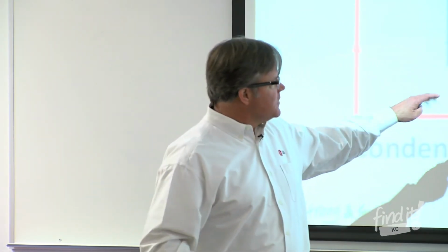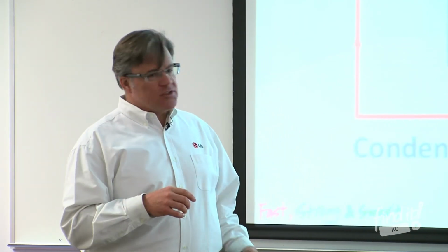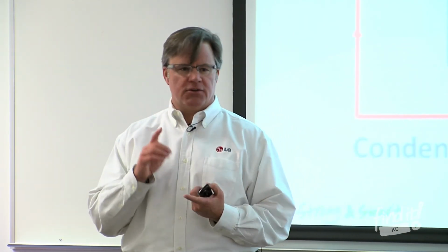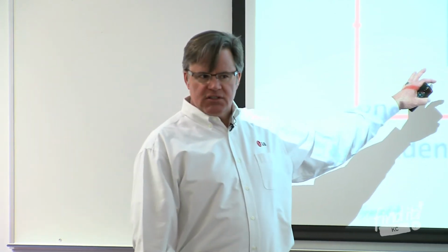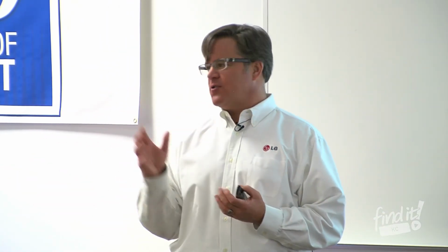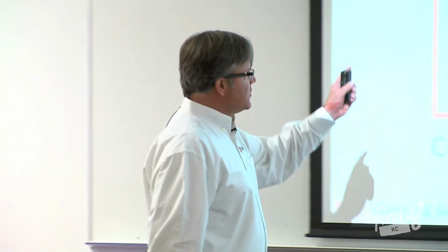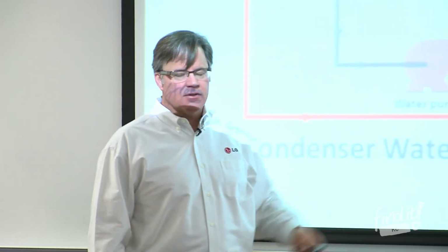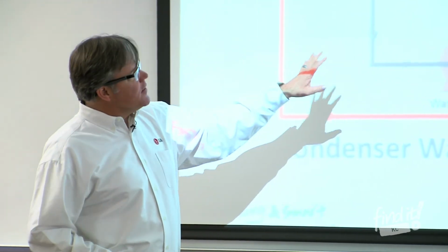This is a very energy efficient way to do that. We also see a lot of folks that deal with buildings in colder climates will go to this type of system, because even though VRF technology will function down to -13, it can get cold enough. You don't have to be too far north of us before your design conditions are colder than that. And so we'll see them use these water systems when they're up against that kind of thing. So that's something that's available.